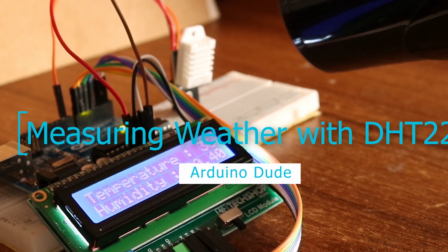Now search for DHT. You need to install this library, which is DHT sensor library. I have already installed it, so I don't need to. Now close the window. Then we defined our DHT pin to be 9 because we attached our DHT pin to digital pin 9 of our Arduino.